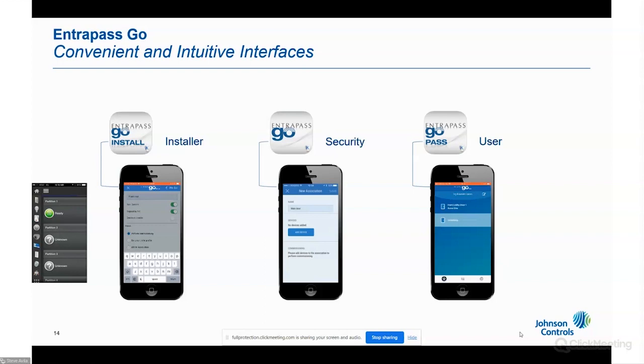It comes with a touch button on the front, that K that you see in blue. It's actually a button that you can program for anything you want, like open a door or open all doors or put the service into maintenance mode or whatnot. Any functionality on the panel, you can assign it to this button pretty much. It gives you head control and enrollment, secondary control and enrollment, like you can make it a master or a slave. And it gives you all the controller status through the LEDs in the front.